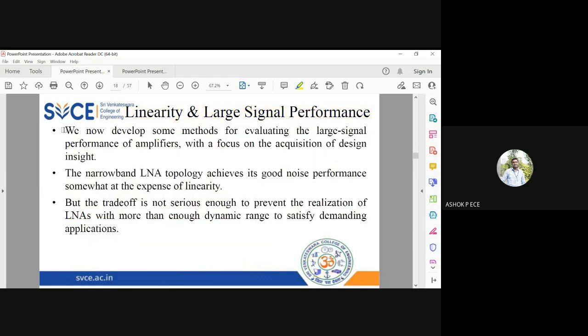So now we are going to develop some mathematical parameters to ensure that the LNA is not going to block my signal, or change the frequency of my signal. And more essentially, it is going to provide very good noise performance, which means that even in a noisy environment, my weakest signal is identified and amplified properly by the LNA. It is going to be actually very tough, but it requires some serious mathematical calculations to ensure that we can implement these two things for a low noise